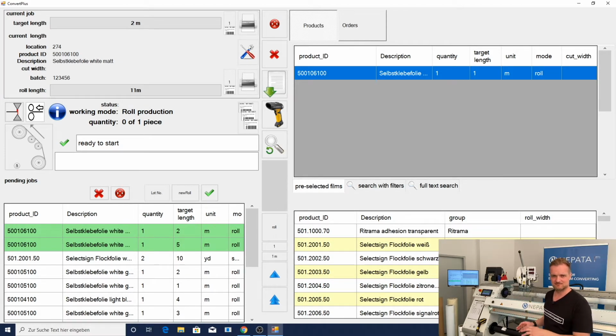It's just working anytime. But the thing is that with material that is mixed, transparent and opaque, for example, printed material where you have sections with ink and sections that are transparent, or with these see-through films that have these small holes inside, the system is confused about seeing something at the light bar and then again it's blocked.